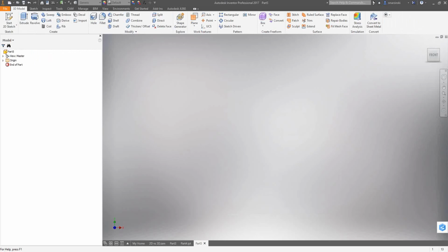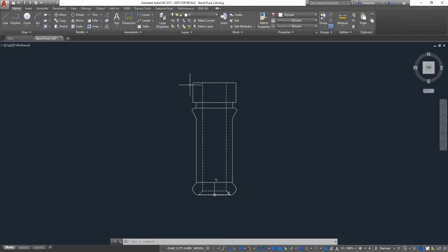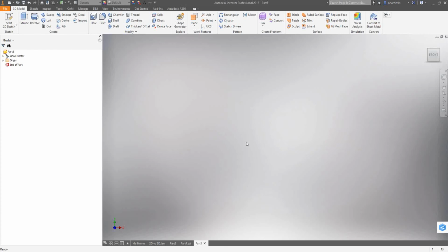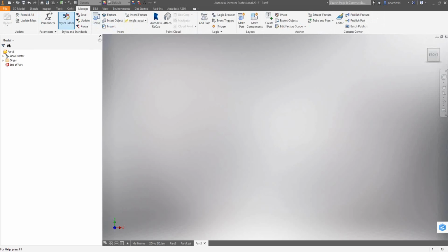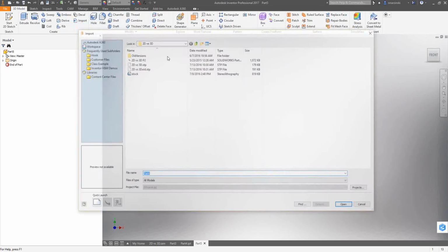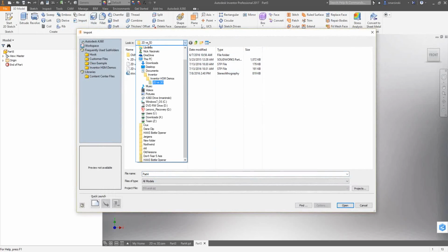In the past, you could jump from program to program and do copy and paste, but then it's just a copy and paste file. You have single objects, and there's no linkage between the two different files. So this DWG, what we're going to do with AnyCAD is import that into here. On the 3D Model tab, you see Import, or on the Manage tab, we also have Import there. So either one works. You go to Import, find that file,